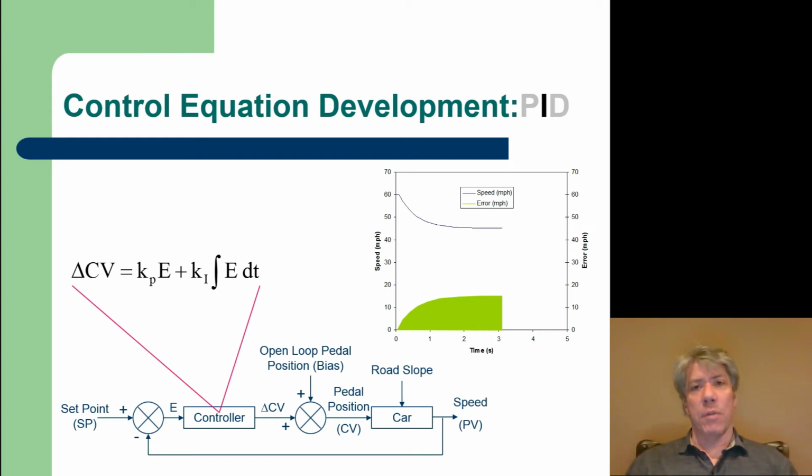What the integration term does is it simply remembers error. It adds it up. That's the way it remembers it. It doesn't remember exactly where the error came from, and that doesn't really matter. All it does is just kind of take, okay, what's the error right now? Throw that on top of a pile, okay?